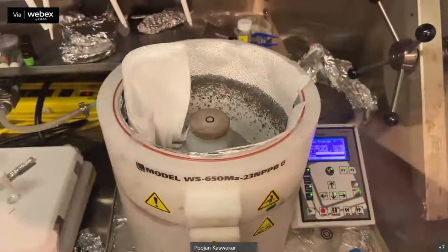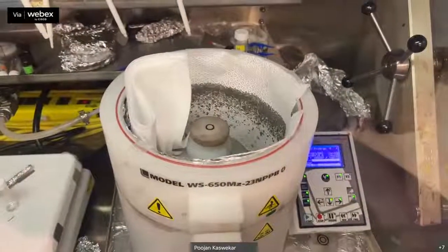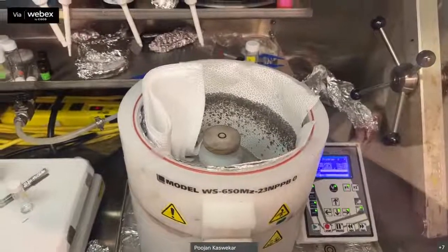paper on the periphery inside this spin coater, so you can easily remove it afterwards. There is aluminum foil inside that one too, but I prefer paper because it will absorb all the materials, so there won't be any cross contamination.